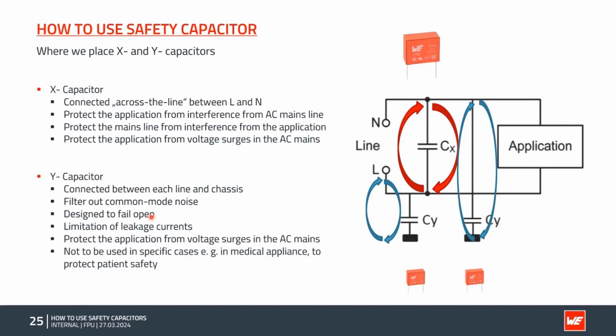It's designed to fail open. This is really important, but we have some limitation about the leakage current. This is why sometimes you are not allowed to use a Y capacitor because of the leakage current, and you have to check with your standard or the definition of the application what is allowed and what is not.